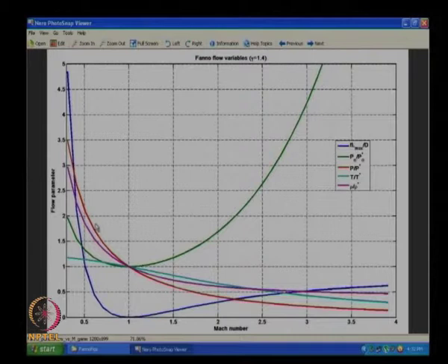Of course, you have to again remember that the flow is going to go only up to M equal to 1. It is not going to keep on decreasing as I increase Mach number, that is wrong. If I am in subsonic, I find that the pressure decreases. If I am supersonic, the pressure increases. Is this logical? Yes it is, because my Mach number is going to go towards M equal to 1 in both directions, and if it is subsonic, it is going to accelerate, which means my pressure and temperature should decrease.